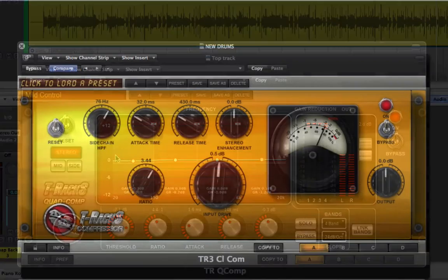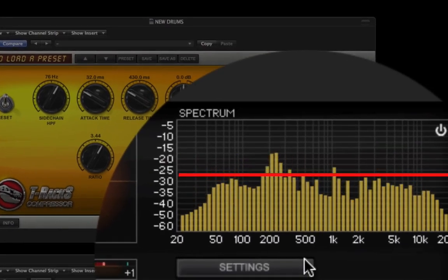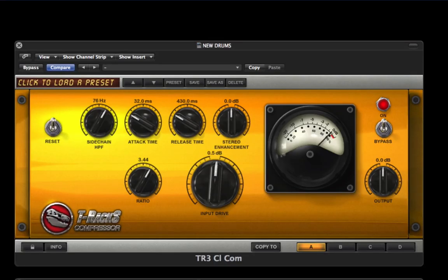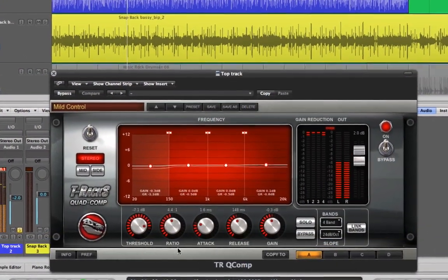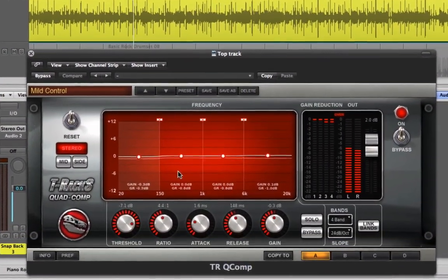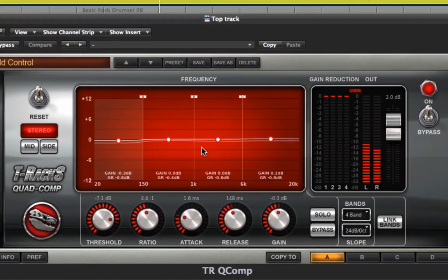Well, a conventional single-band compressor will compress evenly across the frequency range of the audio it's fed. That's great in most situations, but what if there's only one part of the frequency range, let's say a loud kick drum in a whole mix, that's triggering the compression? Then everything will get squashed down every time that kick hits, which might not sound so good. Multiband processing is great because it lets you process selectively within a track's frequency range, leaving the rest alone or processing the other bands less, depending on how you set it.